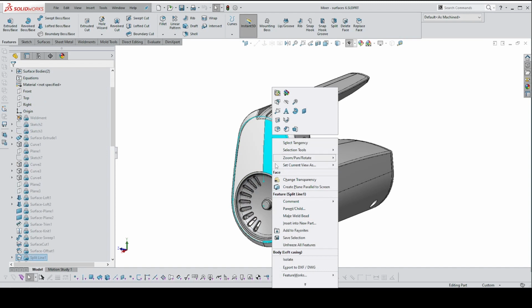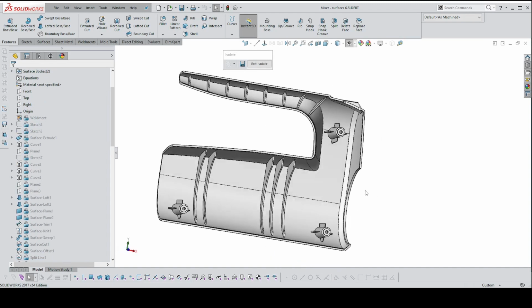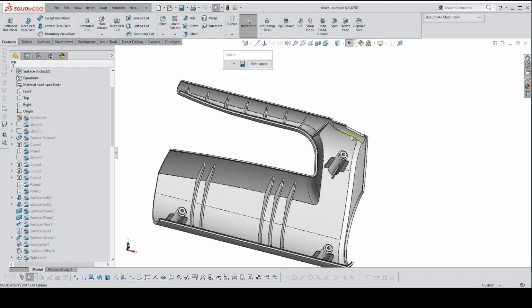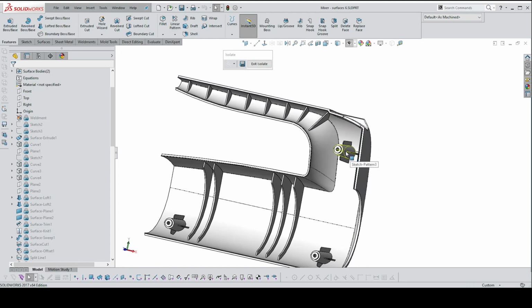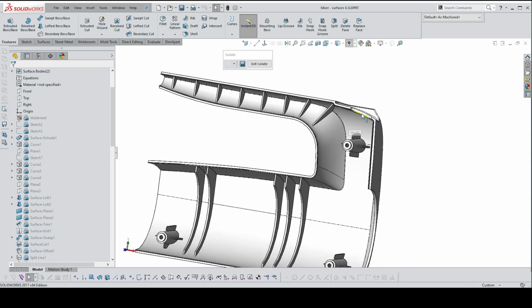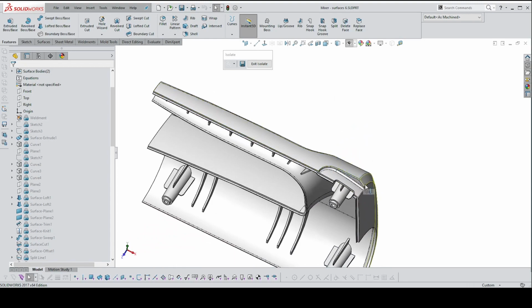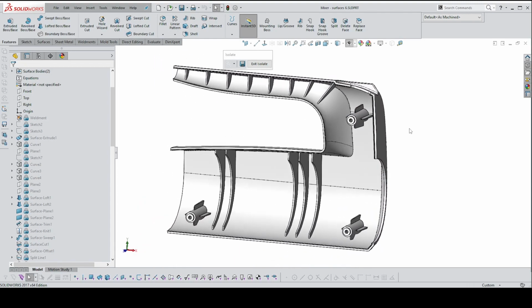Let's just isolate one of them to show you, just to make the molding more doable. So there are no undercuts here. There's an undercut over here, and I've moved this head mounting boss down a little bit so we can get that item out. This typically I'd also cut out and it would be a separate part, but I'm not going to worry about that for now.